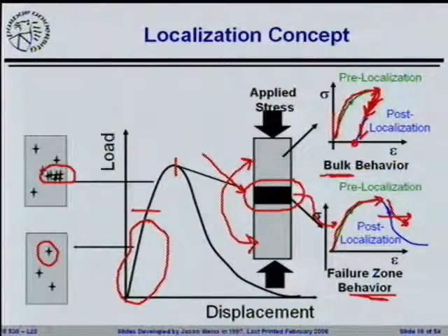So what you can start to see now is that this is starting to make sense. What we've got is this localized region that's going to be a fixed length. From a lot of the work that's done here, we show that it's about the size of the diameter. Maybe it starts out the size of the diameter, goes up to about 1.5 times the diameter. The damaged region is fixed in length.